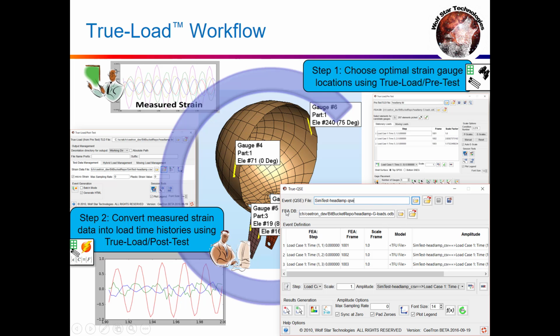We just change out the FEA results, and then it will linearly superimpose the data together based on the loading functions that we've calculated. So this is a very, very efficient way to understand very complex loading on your part in the redesign mode.